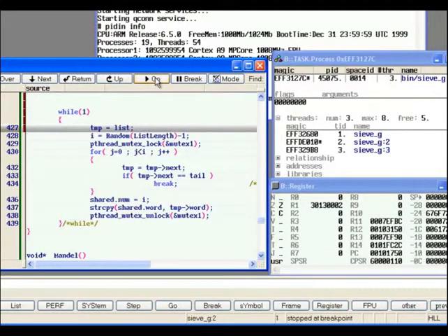So the actual implementation of SMP support in TRACE32 is such that you as a user don't care that it is an SMP system. You are debugging your application, your threads, your libraries, whatsoever, without ever thinking that you have an SMP system. The debugger itself takes care of everything that's down there and hides the SMP system from the upper layer. Of course you still have the possibility to manually edit the individual cores, but usually if you're debugging an application you don't care about the cores. So to sum up the SMP support: you have control over each core that is used in the SMP system. You can edit each core and you can look at each core, but when debugging an application TRACE32 tries to hide the SMP stuff from you so that you can concentrate on debugging your application without even thinking that it is an SMP below.